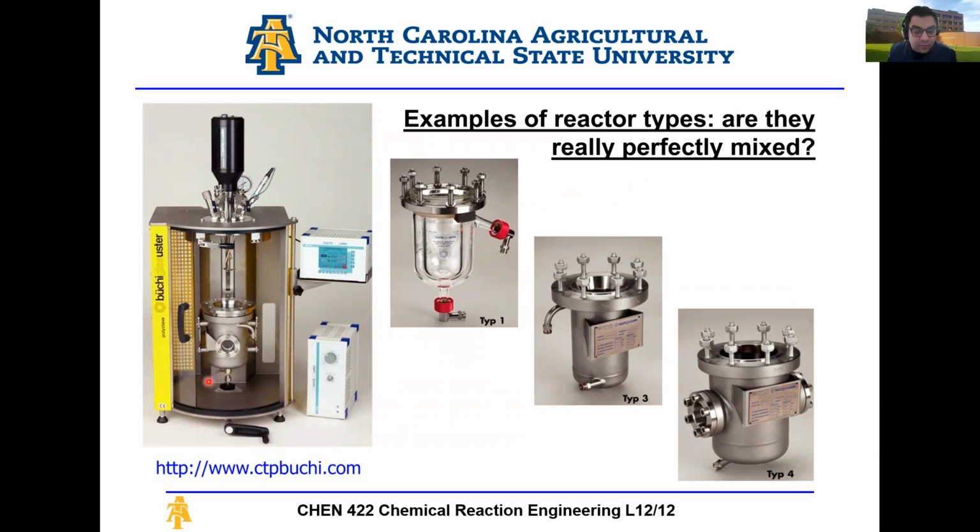If I compare this performance to this CSTR, to my ideal CSTR performance equation, will they match? If they match, then this reactor is perfectly mixed and my assumptions are valid, and this is actually what happens. However, in reality, even at this small scale, you'll find that there are deviations in performance.